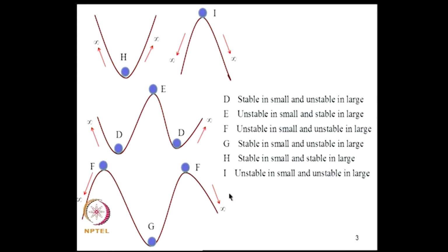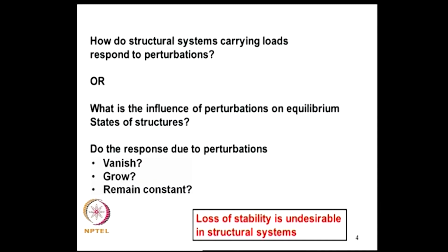Now, we are talking about the motion of a ball in a valley. How do structural systems which carry loads respond to perturbations, or what is the influence of perturbations on equilibrium states of the structures? On account of the perturbation that we give to the structure, do the responses due to perturbation vanish, grow or remain constant? This is the type of questions that we are interested in addressing.